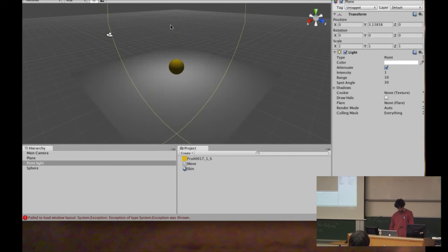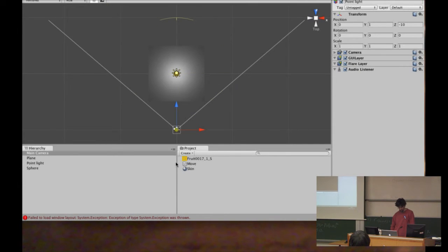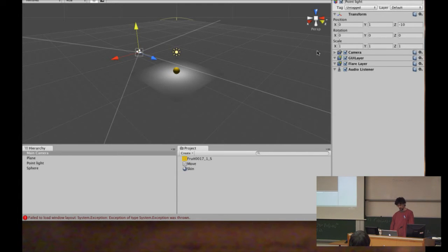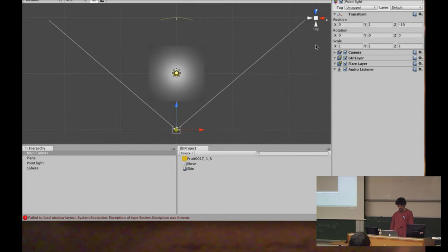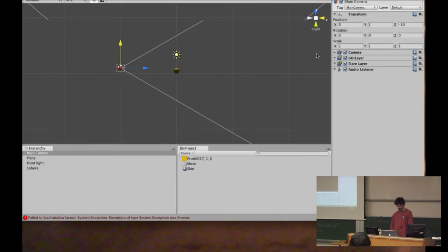Where's the camera? A lot of you noticed in last week's shoot that we were getting a bit lost in the scene. It's hard to work out in the 3D view whether or not that camera is actually pointing at that ball. It's very handy to use these different views. You can see now that camera is pointing in the x-axis. From above, yes, it's pointing the right way. From the side, yes, it's pointing the right way. And so we know that it's actually pointing at the object.